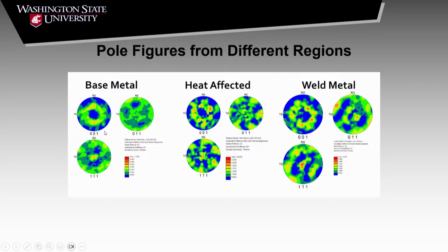However, it's actually a conceptual thing. That means that my fiber, showing in the 111 pole figure, is still represented in the 001 and the 011 pole figures. So it doesn't matter which pole figure I'm representing, my fiber is seen in all three figures. So the 3 pole figures are showing the exact same distribution. That's what you mean, right? Yes, it's showing my fiber.